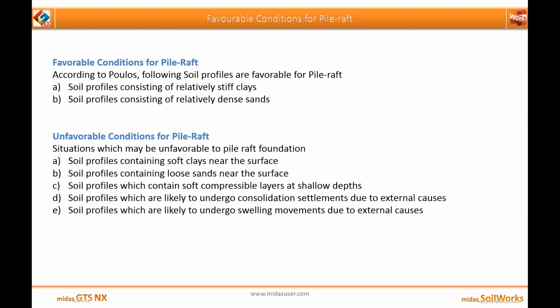Now, the unfavorable conditions, where one shouldn't go for pile raft foundation, are soil profiles containing soft clays near the surface or loose sands near the surface, soil profiles which contain soft compressible layers at shallow depths, soil profiles which are likely to undergo consolidation due to external loads, and soil profiles which are likely to undergo swelling movements due to external causes.